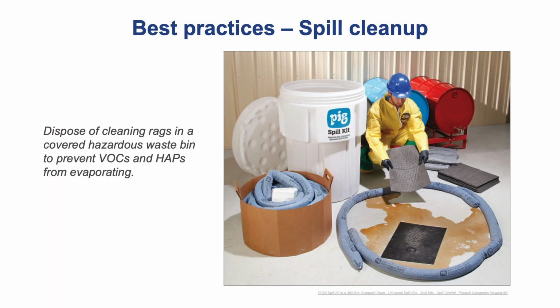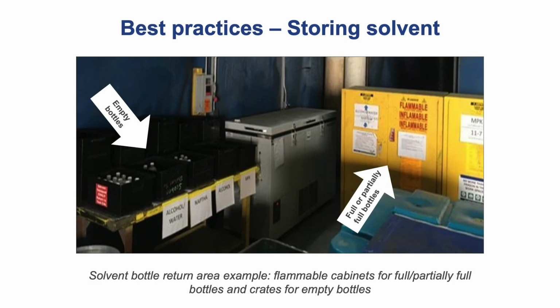If solvent is spilled, clean it up immediately and dispose of cleaning rags in a covered hazardous waste bin to prevent VOCs and HAPs from evaporating. Ensure solvent is being stored and disposed of properly according to your company's policies.